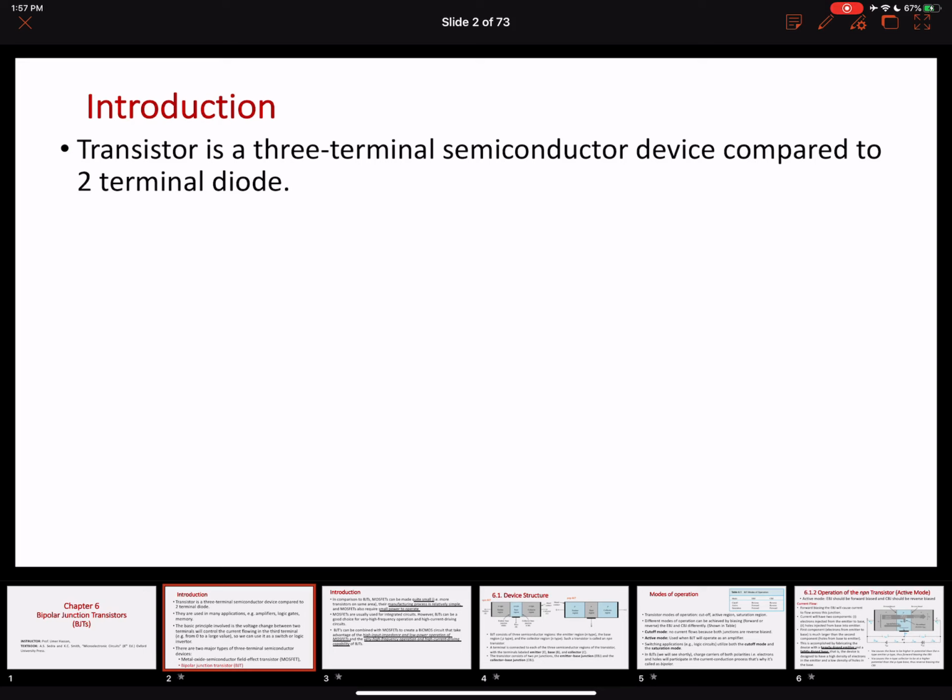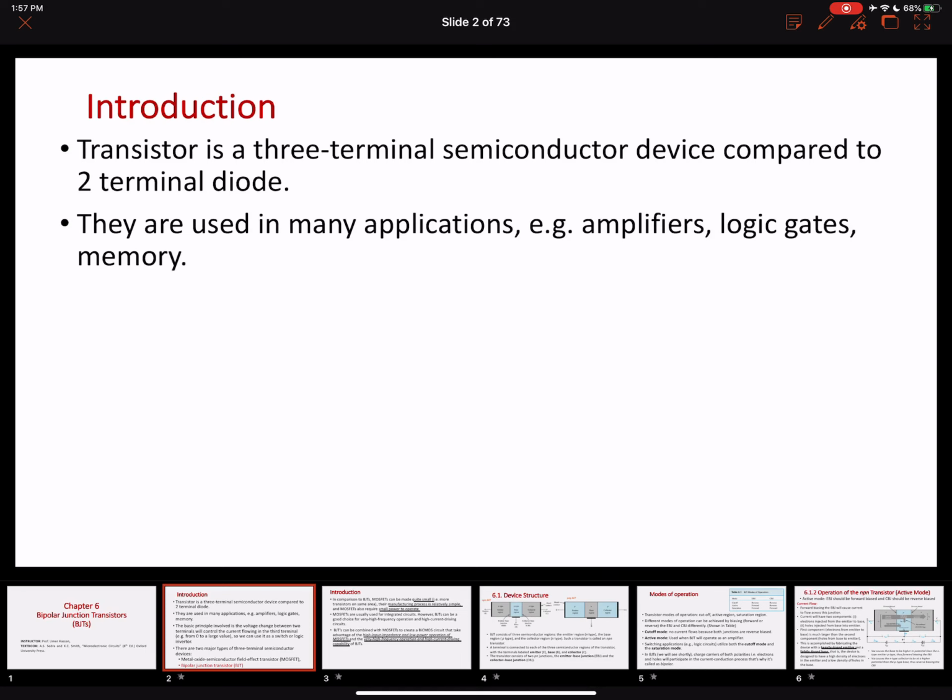Okay, so our diode is a regular PN junction, and that's a two-terminal device, and our bipolar junction transistors are also regular PN junctions. They are much more closely related to the diodes. You will realize that soon. And they have three terminals. We can make them by combining two PN junctions together. We're going to discuss that shortly.